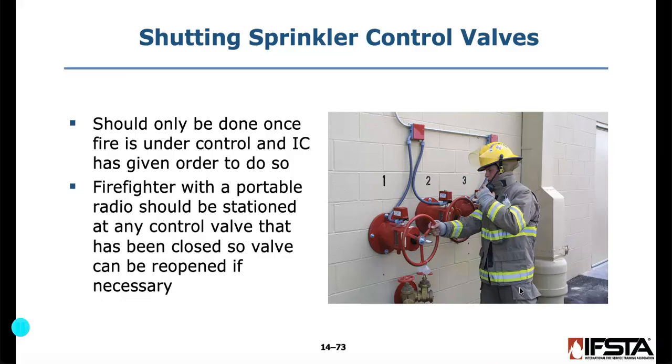This should only be done once the fire is under control and the IC has given the order to do so. And then a firefighter with a portable radio should be stationed at any control valve that has been closed so the valve can be reopened when necessary. Depending on your department policy, we don't recharge the systems. We don't fix the systems. We'll put the building on fire watch, and then they'll have to get their system fixed because we don't replace sprinkler heads. They'll have to have somebody come out and do that. And then once that's done, they can get their system certified by an inspection company and then charge their system back up.